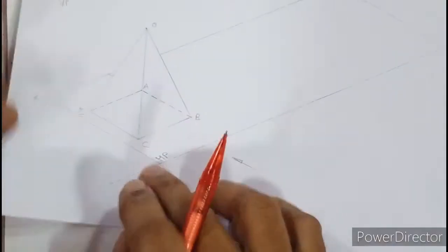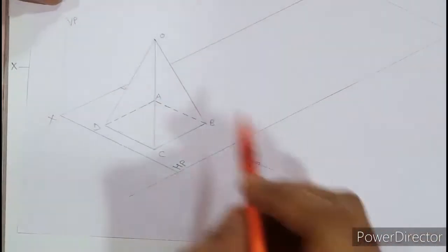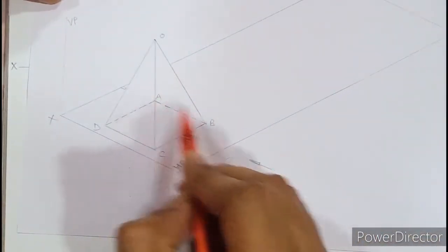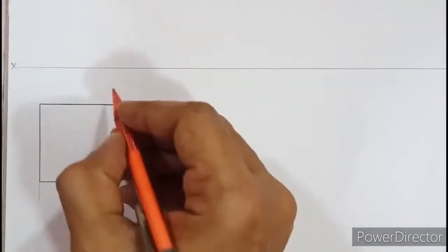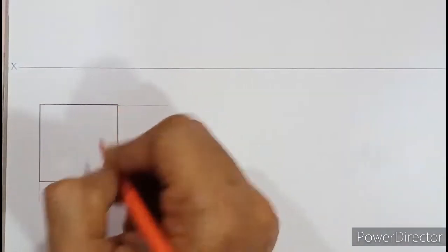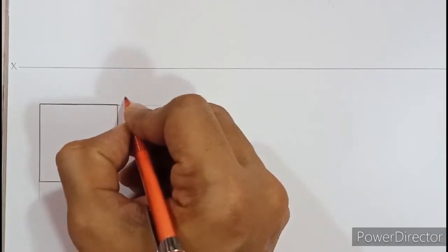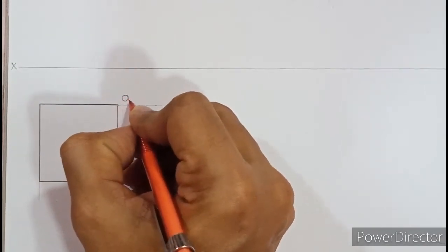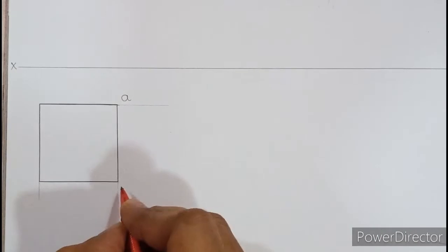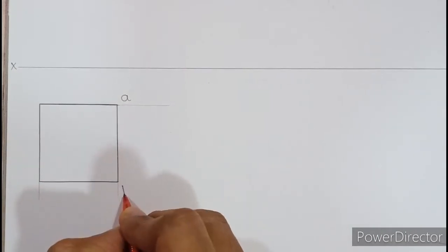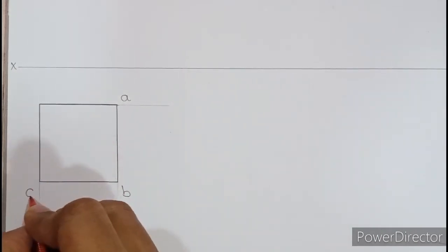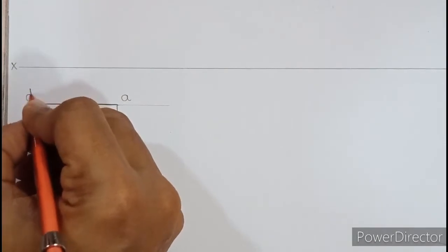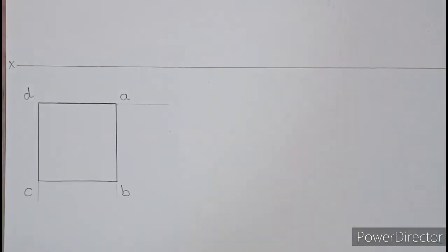So referring to this diagram, in the top view we need to name ABCD. So always in the top view we will follow a systematic way. From the right side top you can start naming small a, so name outside the corner, and clockwise sense you can name this as B, C and D. So this ABCD should be medium dark.